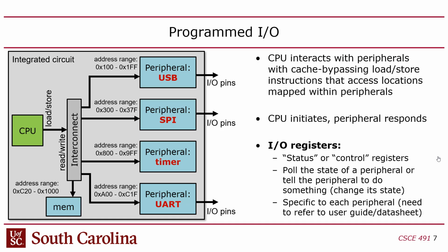The peripherals can be I/O interfaces, like this is an SPI interface, right? You could think of this like a network interface that ultimately goes off chip, but the CPU talks to the SPI peripheral, and then the SPI translates load and store instructions to the SPI serial protocol. Right? Does that make sense? Think of this as a network interface chip, network interface adapter, essentially, right? But this peripheral is on the chip, right?